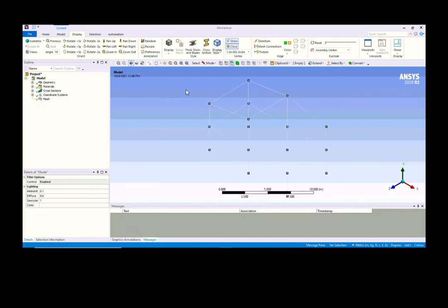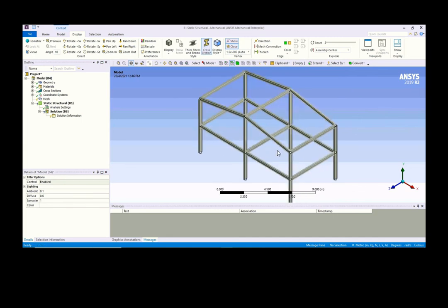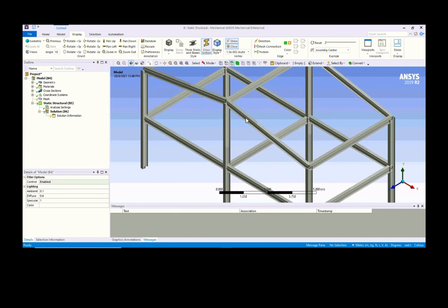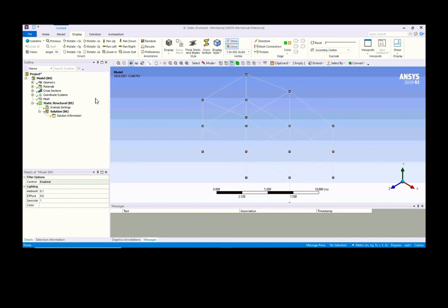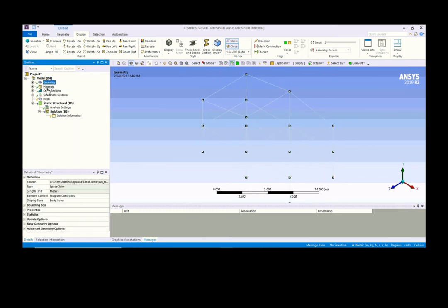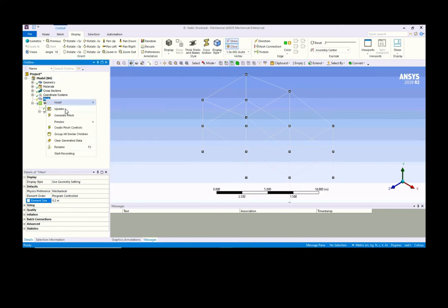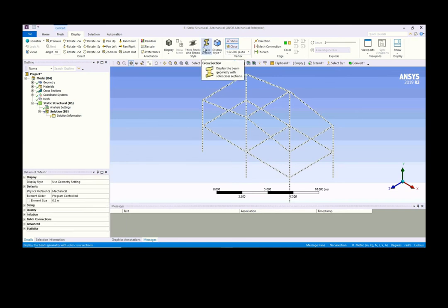Okay, so I have the model out. So if you want to see it, basically it's this in the cross sections. So all are in I-beams. Okay, so I have tried to orient it already. So what we do is material, make sure it's the correct material. Then mesh, we can play around with 0.2 similar. Then you can generate mesh. So if you look into this, that is a similar thing.